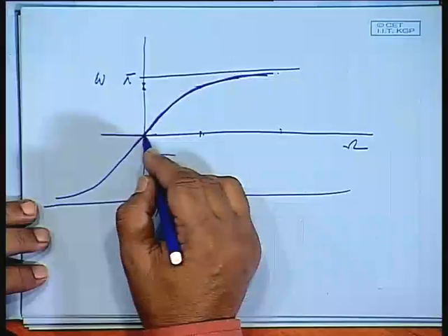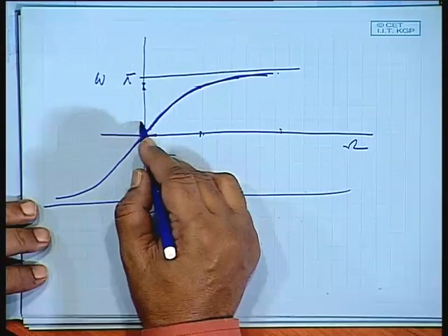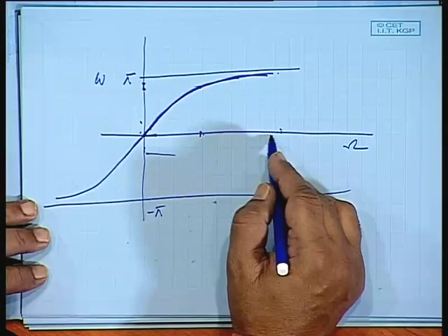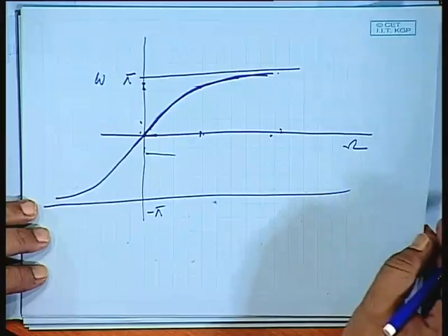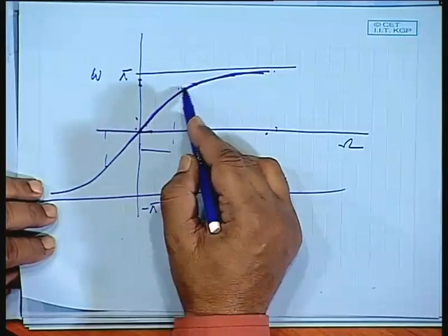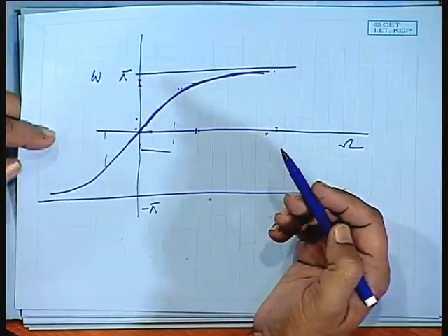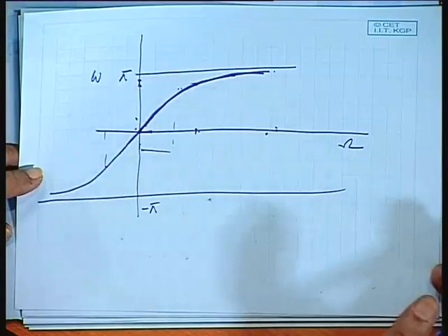At a very low level it is proportional, but at a high level it is distorted. It is distorted in this, say beyond 30 degrees or so, you will find the distortion is quite prominent. So, when we give a specification for any filter, we must ensure that such distortions do not take place. This is known as the warping phenomenon.